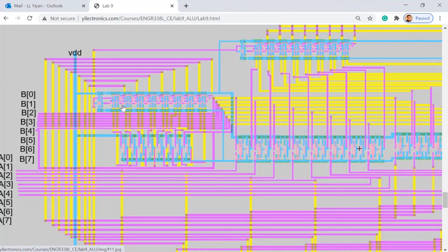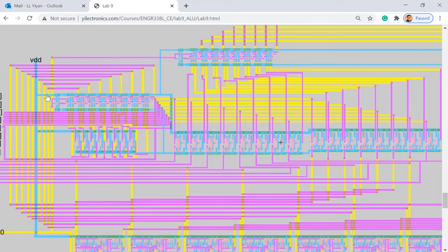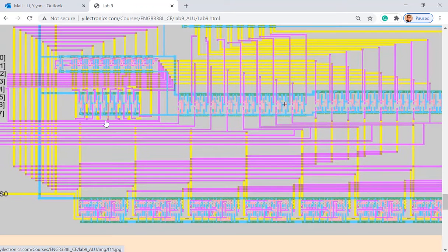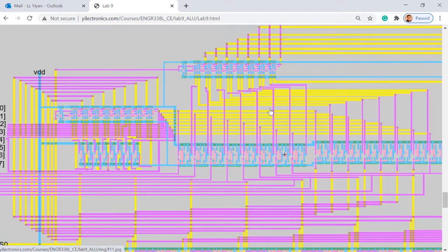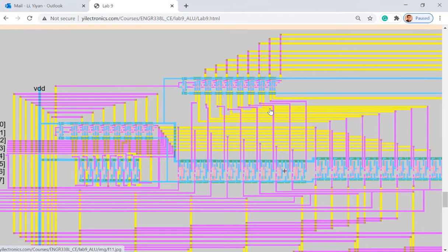I'm going to use it at one moment in the future when I'm forming this ALU. So later on, if I need it, I directly drag the entire multiplexer subcell to this layout view, put it here and make the connections. It's the same as all the other ones. I just have to do it one by one. You need to have all different levels of subcells.